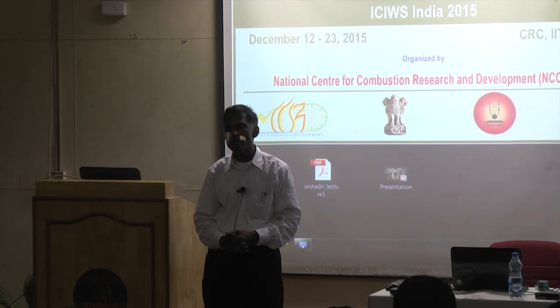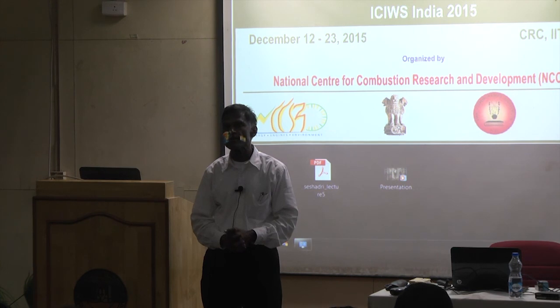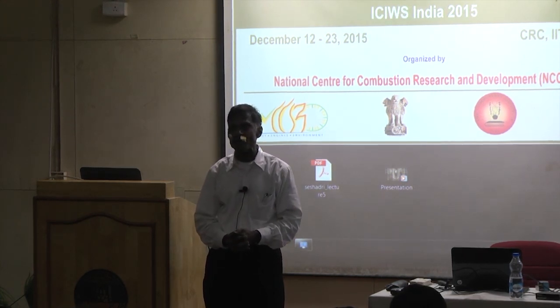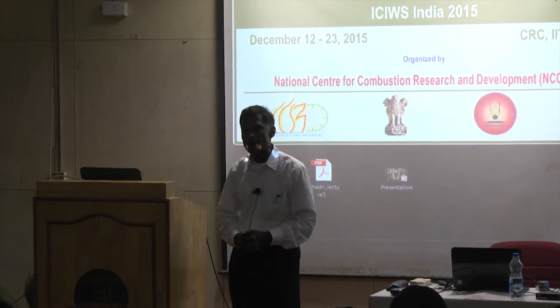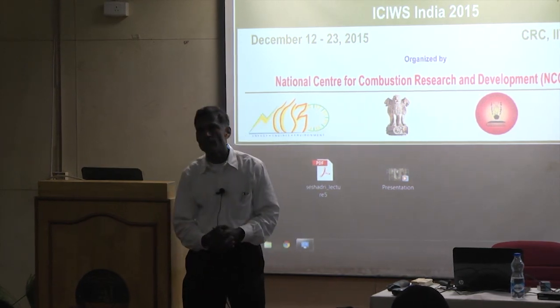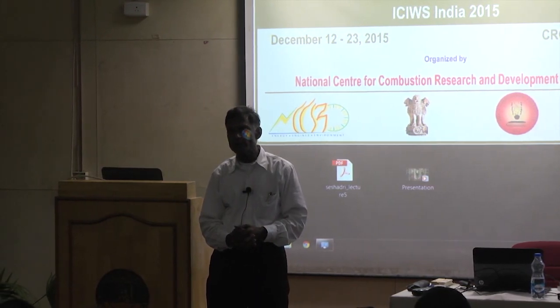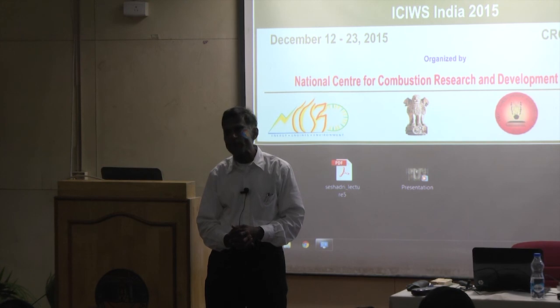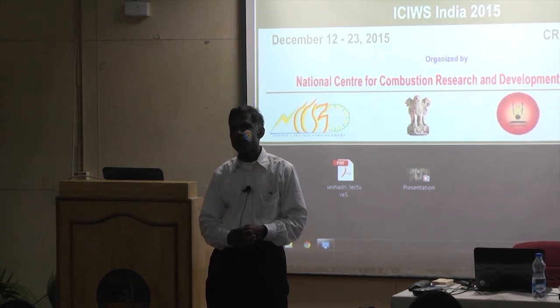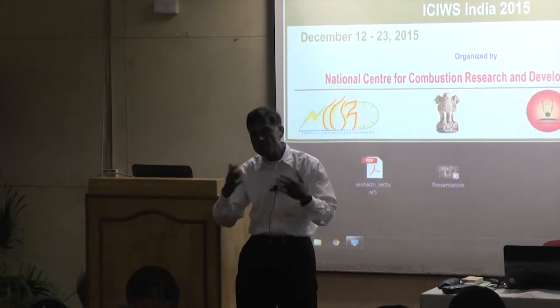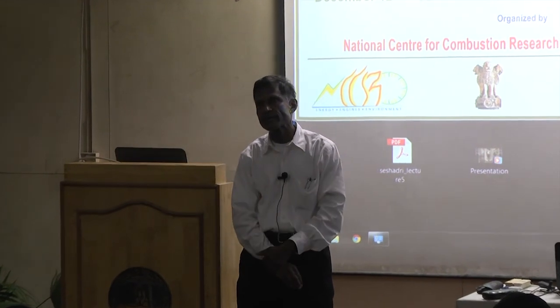But has any study been made, how does it compare? No. In fact, most likely the study is not necessary, and if you even do that, it will probably fail. Another one, how does the flame temperature compare, the surrogate and JP8? We have not measured flame temperatures, but I would expect they're not that different because the heat release rates are similar, and extinction strain rates are the same, so one would expect that to be similar as well.